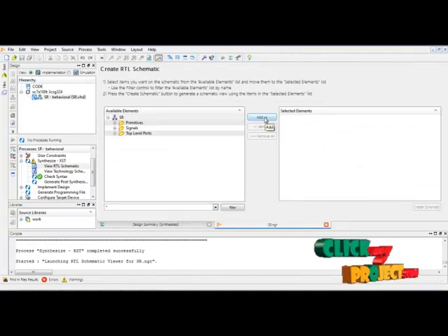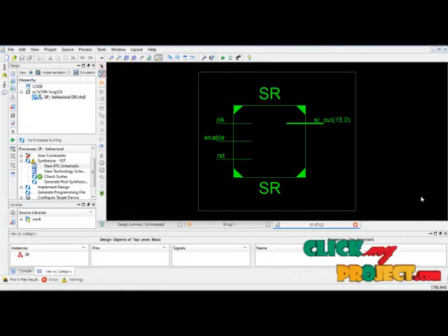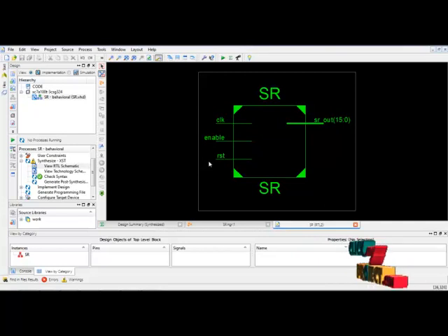Now click the Add button and click Create Schematic. This is our overall schematic diagram. The input pins are clock, enable and reset. At the initial stage, we reset the given input, and afterwards, for each and every clock period, we generate the clock and generate random numbers in the SR output register. The output pin SR out contains 16 bits. Thus we generate 16-bit random numbers.